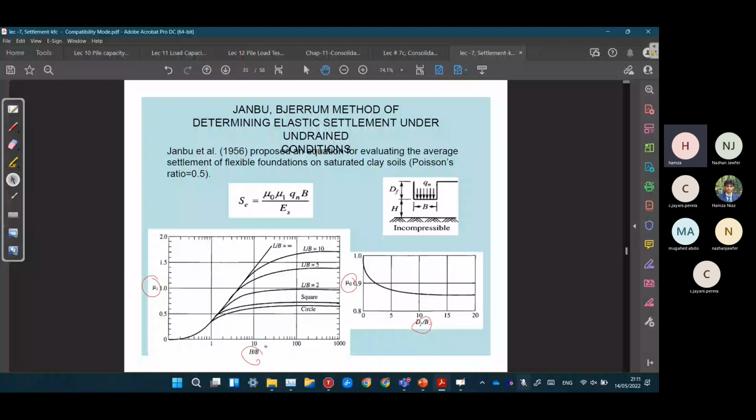For example, this is a group of piles. So these are the length of the pile. So at 2/3 of the length, we are going to calculate these values. At 2/3 of the length, what would be the contact pressure? For example, this is 8.6 meters.